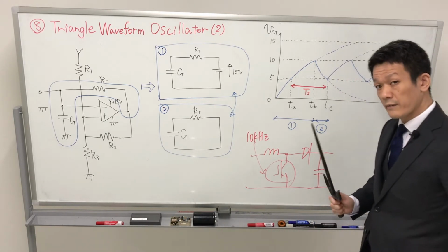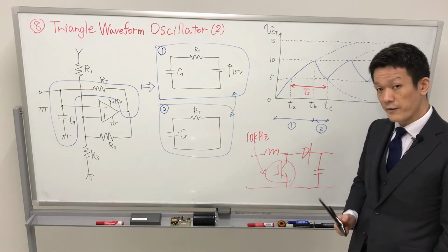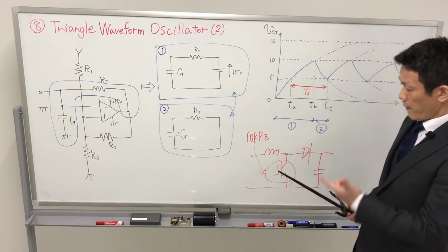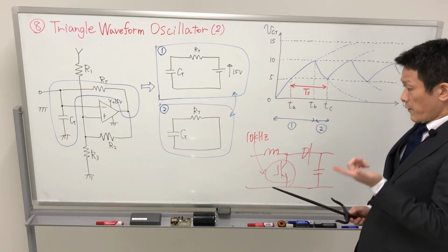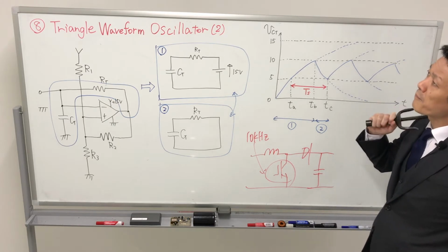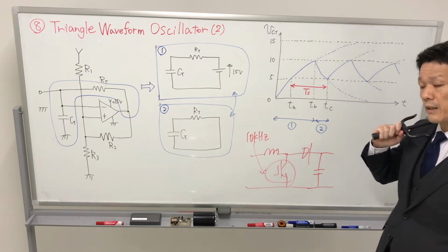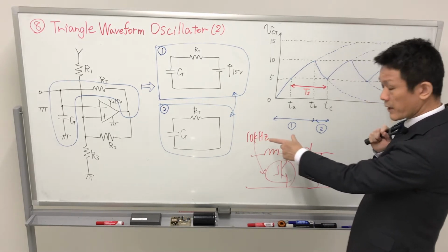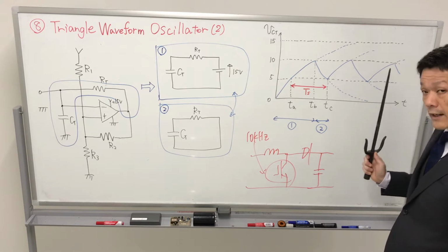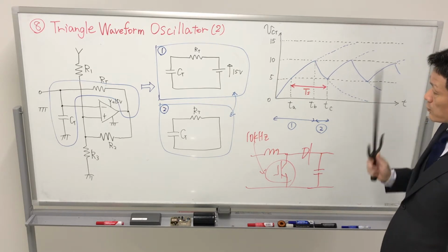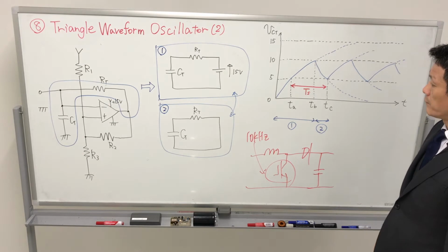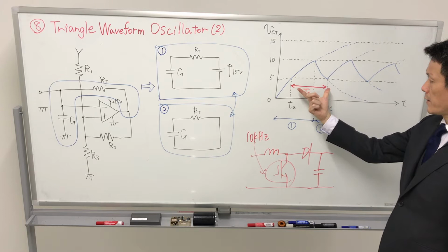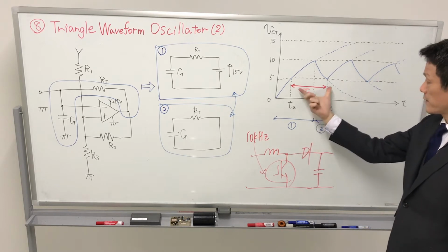Please design the 10 kilohertz switching frequency for this boost chopper. We have already mentioned in the PWM control lecture that this switching frequency decides this triangle waveform. The timing TS, the period, is decided by the frequency.